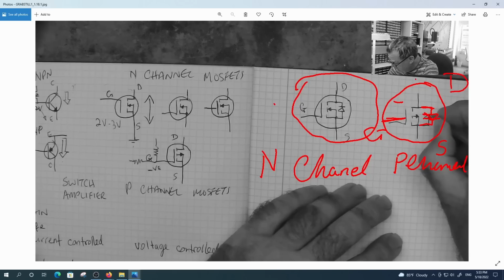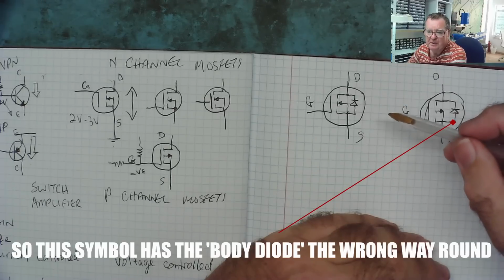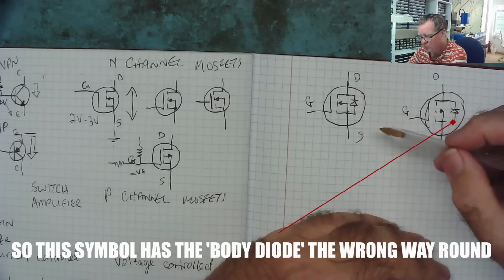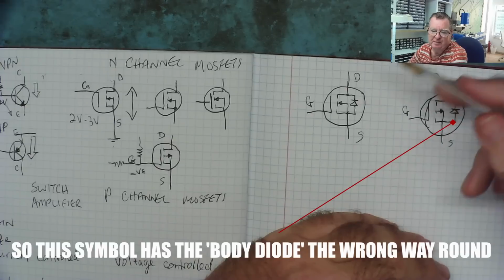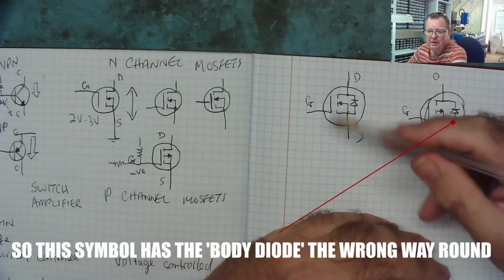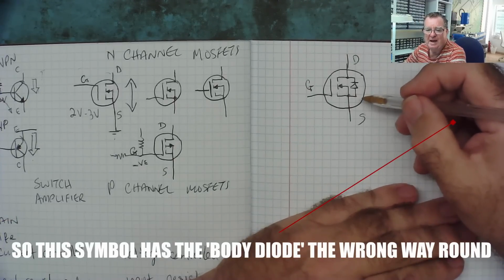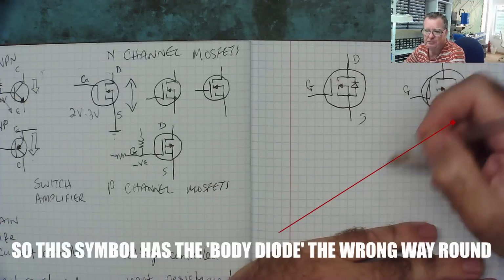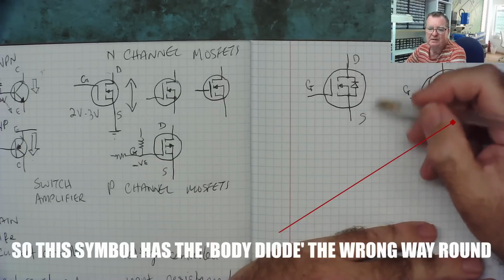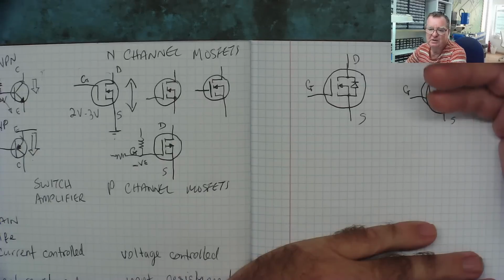Let's continue. Now you might wonder, why do they put a diode in the MOSFET? And you also might wonder, if you know anything about buck regulators and circuits that are switching relays and inductor coils, is it there to take away what's called the back EMF? Well, the answer to the first question is they don't put a diode in the MOSFET. The diode is there because of the way that the MOSFET is constructed. It's a byproduct of the construction of the MOSFET. That's why the diode is there. It's not deliberately put there. It's just a byproduct of what the MOSFET actually is internally.